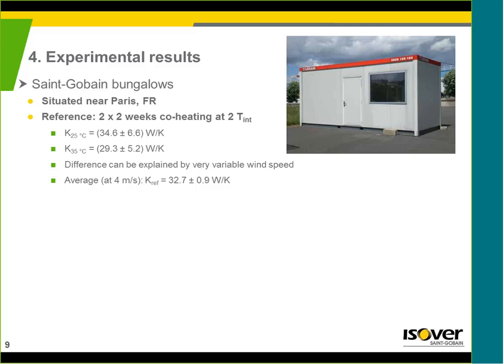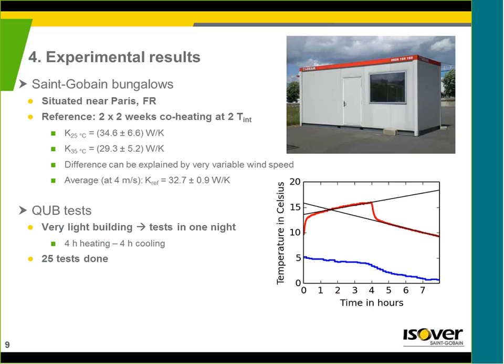I wanted to add that because the bungalows are very light structures, very small, etc., 4 weeks of co-heating might be equivalent to 2 or 3 months of co-heating in a standard heavy house. So this is, I think, a very accurate result. So we compared it to our own cube test, because we have bungalows just near the buildings where we work, we could do a lot of them. And as I said, because the buildings are very light, we could do what was not done at first in real buildings, but test in one night only.